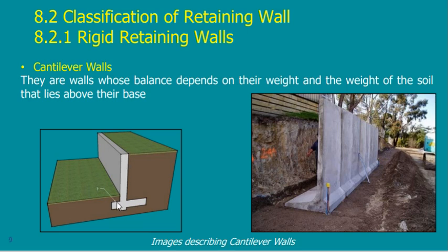So this would be the shape of the wall. This is the higher side and this is the lower side. And this is a very slim wall. This wall wants to move outside. What will prevent the wall from the motion? It is reinforced. It can carry tension. And if the soil tries to push, the wall will resist, due to the ability to carry moment. So it will carry any amount of moment according to my design. So this is a cantilever.